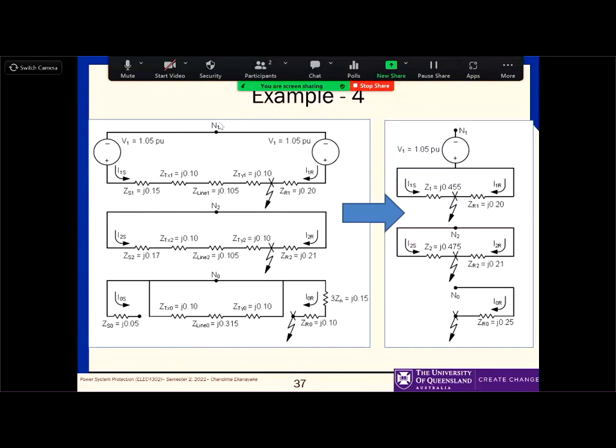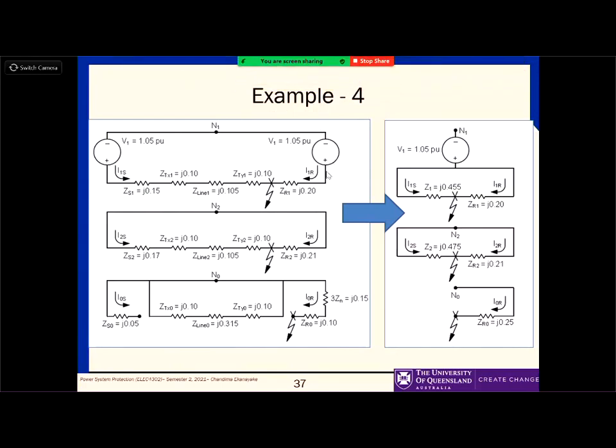You can put all impedances and then find where the fault is. So now you have two circuits in parallel, this part and then this part, right? Because from the fault location you will have two generators. If you have three generators, all three generators are in parallel from this location, right?